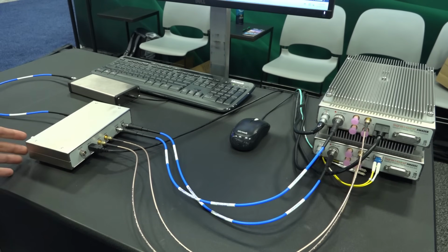And one of the other things you can do is this itself is connected to the Spike software, so it has control voltages, so you can do complete VCO characterization. That's a really critical aspect of it, because you cannot do cross-correlation phase noise unless you can lock a free-running VCO to do that measurement.